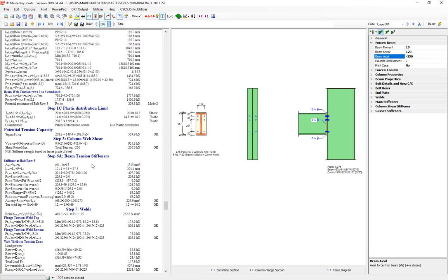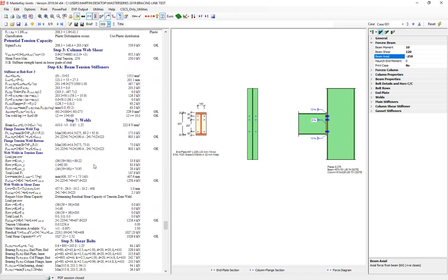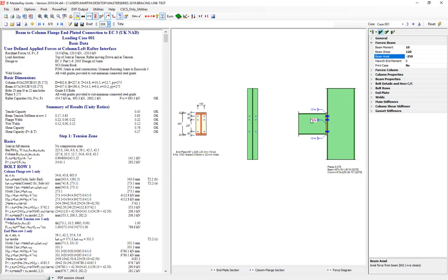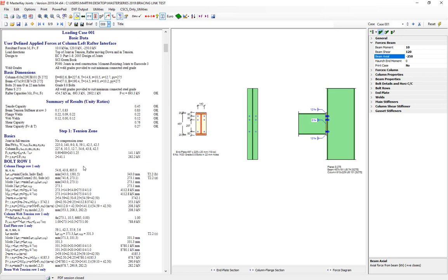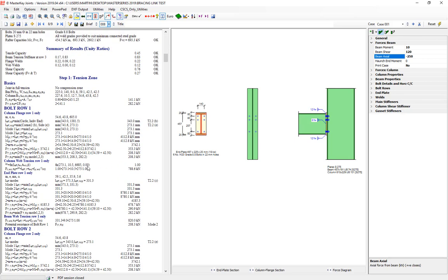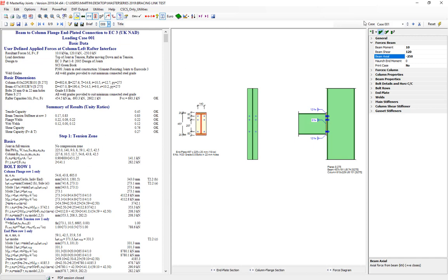A little bit more complicated in this instance because of some modifications that are required for the bolt row capacities, which are primarily set up previously for a distribution of top down, whereby you've got tension on the top dissipating to quite low value of tension on the bottom. So that required quite a bit of significant work to actually make that work in a sensible engineering way. So the joint is in full tension here, and the capacities are readjusted and redistributed in a very appropriate way, without getting into too much more on that at this moment in time.